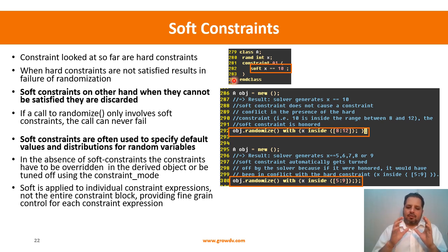Now what I need is some default constraints to take effect. If I'm not passing any value, it should take the value from that particular range, and if I pass a particular value, it should be that specific value only. Now it's very simple. I can put a regular constraint, and then when I'm randomizing with, I can take a specific value. So let's say I'm randomizing between 1 to 10, and then I'm passing via command line argument a value of 8.